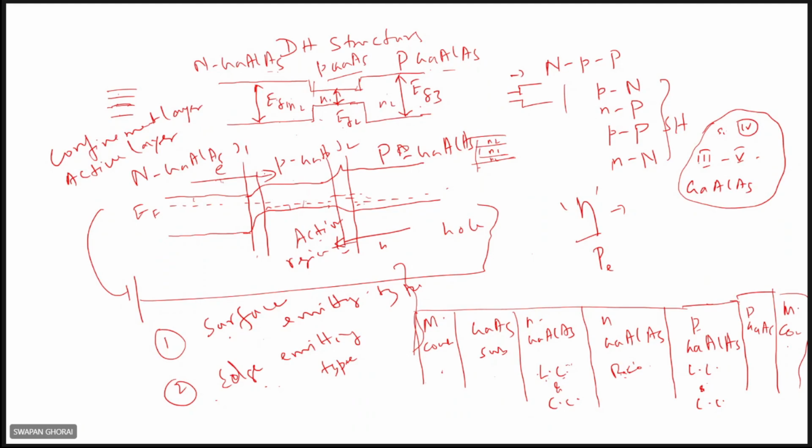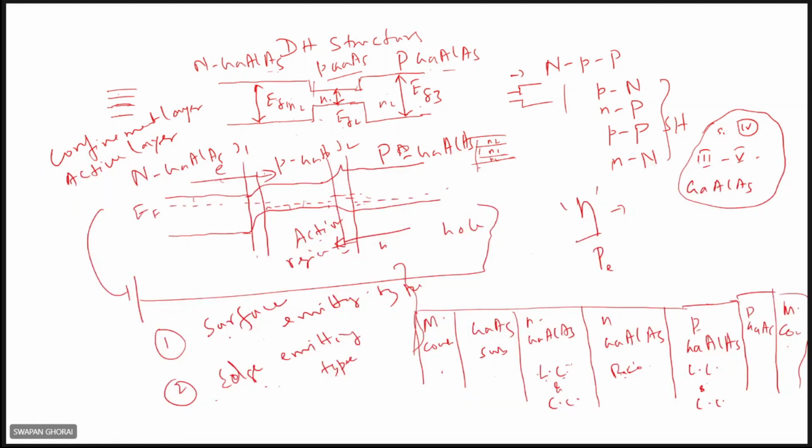And high internal efficiency is basically a combination of electron hole pairs and radiative recombinations. So in that case, the efficiency should be high. That means the fraction of radiative electron hole pairs should be more; radiative recombinations should be more compared to the other recombinations. So to achieve these three factors, you have to have optical field confinement and charge carrier confinement. And for that you need DH structure, double heterostructures.